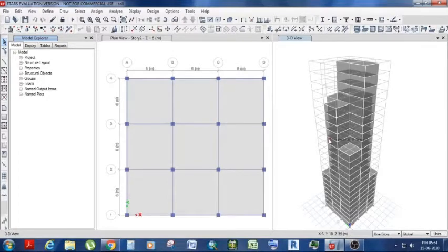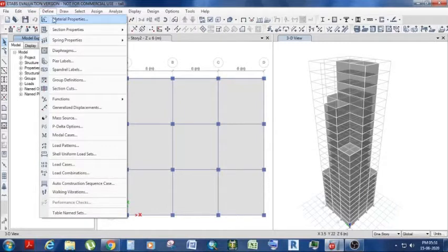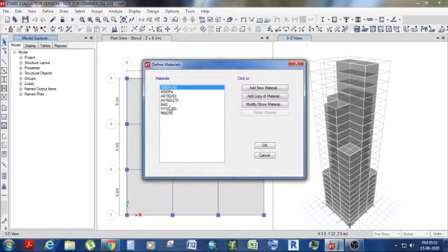In this video I am creating the Seismic Design project assignment for the Skyfi Labs online course. This is a model which I have created for the seismic design, done using the response spectrum method and time history analysis. The structure has been created by assigning the material properties M40, HYSD 500, and mild steel 250 bars.